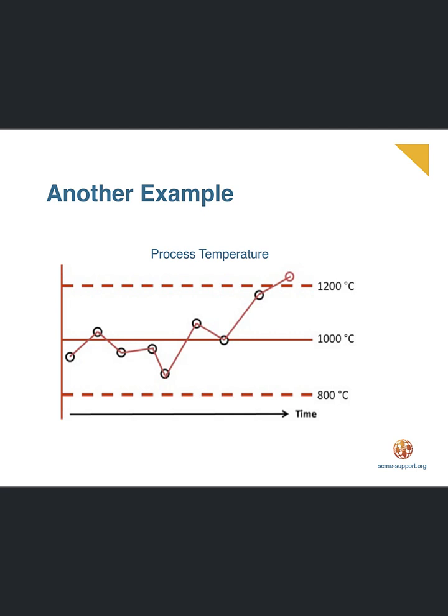After an investigation, an example of a root cause for this sudden jump in temperature may simply be due to not enough coolant in the cooling system. The cooling system could be checked. If a coolant is needed, it would be added to alleviate the problem. If that was the cause of the problem, then the collected data on the next run would show the process back in control. If not, further investigation into the cause of the problem would be required.